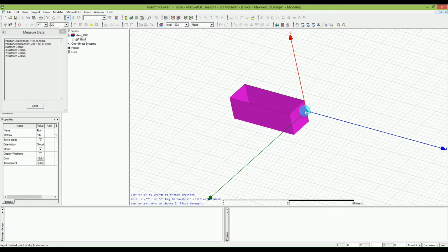So now you have to select which coordinate for the line and then how much do you want to duplicate. Again, you can just select here. As you can see, if I select here, it automatically is snapped to the 0, 0, 0. So I'm gonna use mouse for this purpose and just click.